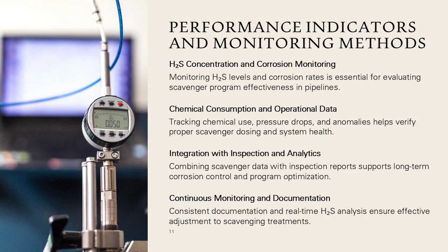Integrity teams may integrate scavenger performance data with inspection results such as intelligent pigging, ILI reports to validate long-term corrosion control effectiveness. Consistent documentation supports optimization by enabling adjustments to injection rates, chemical type, or treatment locations. Thorough monitoring ensures that scavenger programs remain effective despite dynamic production conditions.